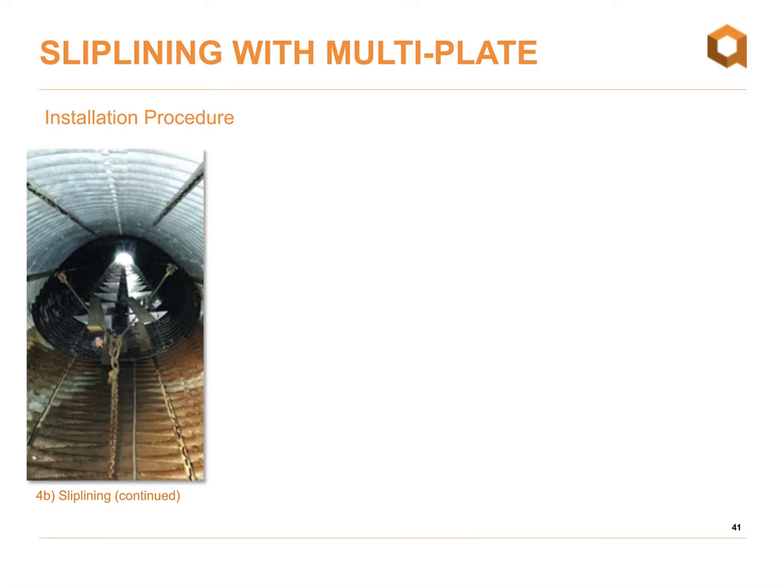In terms of actually pulling the structure through, it's fairly simple. Usually we just recommend putting eye bolts through the bolt holes along the end of the structure. So that's what the contractor did in this case. This was a 97-meter long pipe. We had a structure under about 20 meters of fill. This is along Highway 97C, just outside of Kelowna here in BC. This is a structure we rehabilitated in 2014. It was just pulled through with an excavator. So fairly simple. You don't need a lot of heavy equipment to actually pull these structures through, even for fairly long culverts.